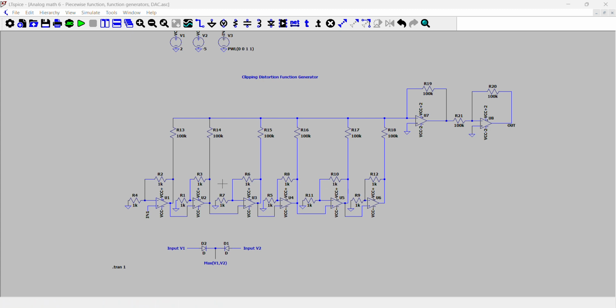And normally, if we summed up all of these voltages, what you end up with is a constant line, so a constant function with regards to the input voltage. However, because the amplifiers have a rail voltage that they can only go up to, if any of these amplifiers clip, they will actually change the slope of the line at a particular cutoff voltage.